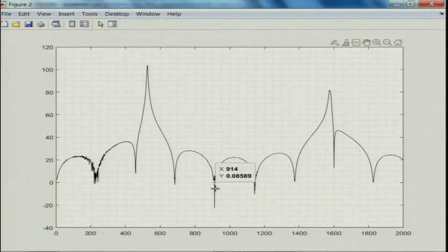Transmission loss can never be negative, at least for a passive system which does not have energy generation inside the system. Transmission loss is always positive. Why? Because it is the logarithm of the ratio of the acoustic power incident to that transmitted downstream of an anechoic termination.